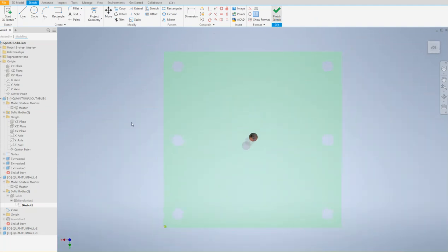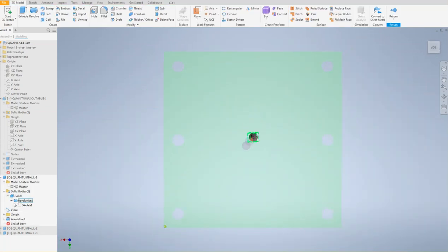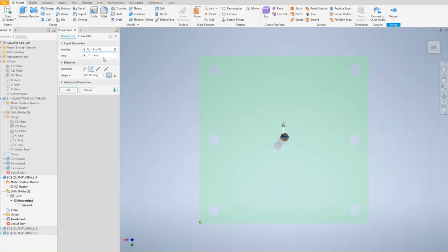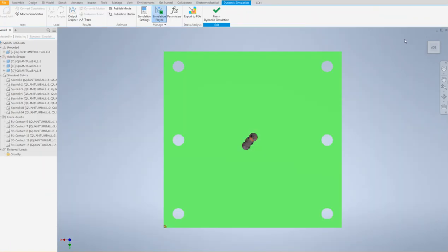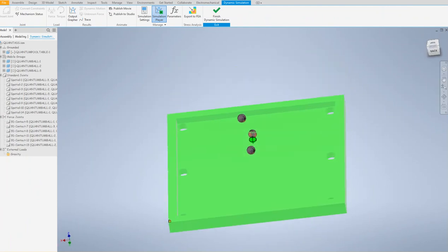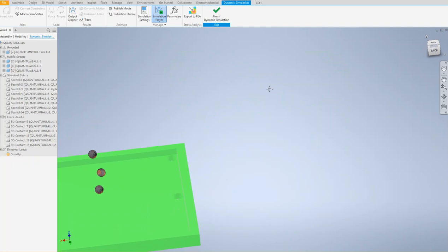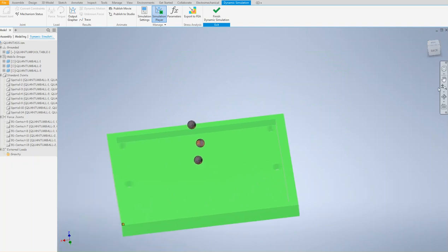So I'm going to finish the sketch to show you the revolve command. The revolution is going to be a 360-degree revolution to create a sphere, a perfect sphere. That ball will be placed or inserted into the assembly drawing. So once you're done, you create an assembly drawing, insert the table, and also you need to insert the balls.